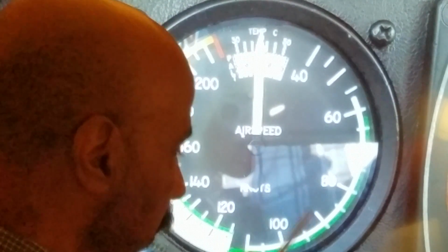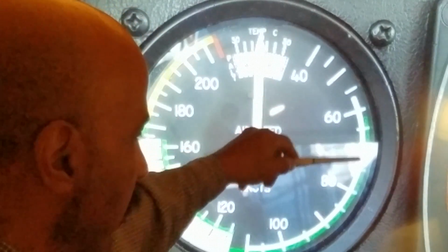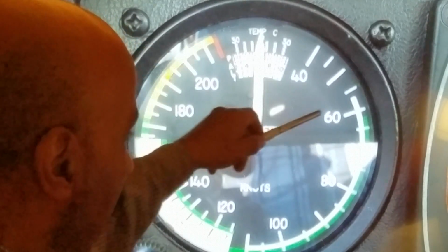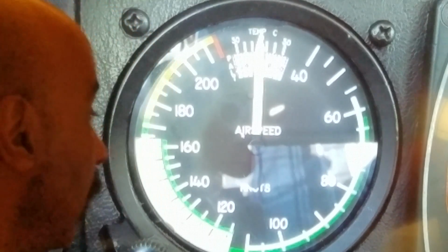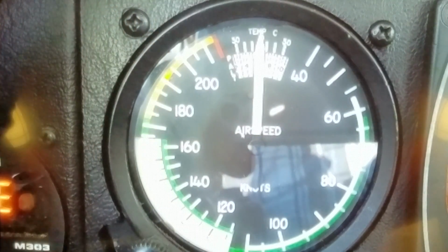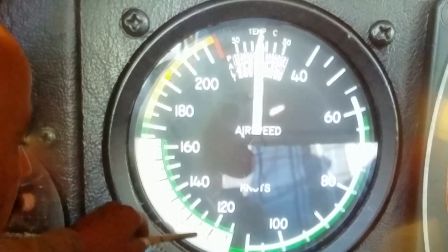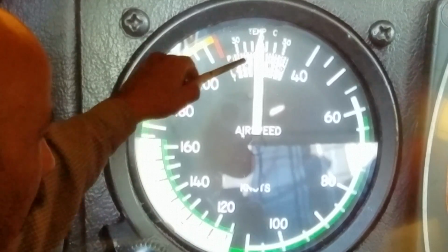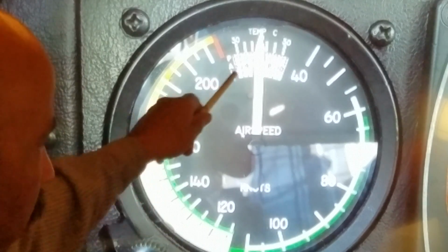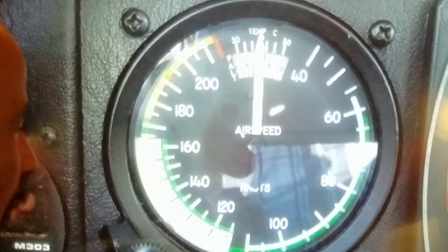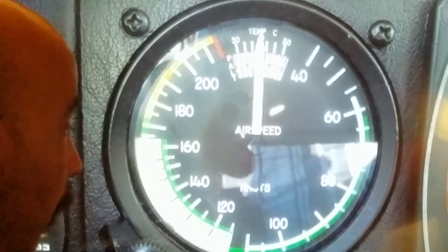The airspeed indicator here has quite a few range markings, is what we call them, and they're placed on the gauge in different colors, and we need to know these colors and the indications that this gauge will give you. Components of the gauge are the knob down bottom left here. When you turn that knob, what you're going to be turning is the inside white scales or cards behind the front face of this gauge. You turn the knob and both these white scales will move. We'll talk about the arcs and what they're for.